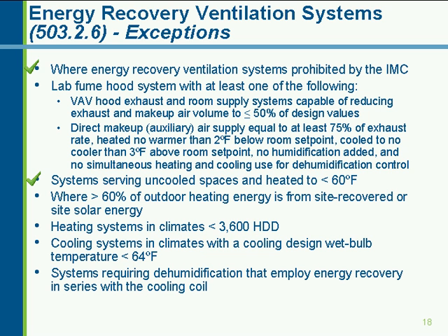Where 60% of the outdoor heating energy is supplied by site recovered or site solar energy, you're exempt. Heating systems in climates of less than 3,600 heating degree days are exempt, and cooling systems in climates with a cooling design wet bulb temperature less than 64 degrees are exempt. Systems that require dehumidification that use energy recovery in series with the cooling coil are exempt, and really what they're exempt from is the efficiency requirement, the requirement for